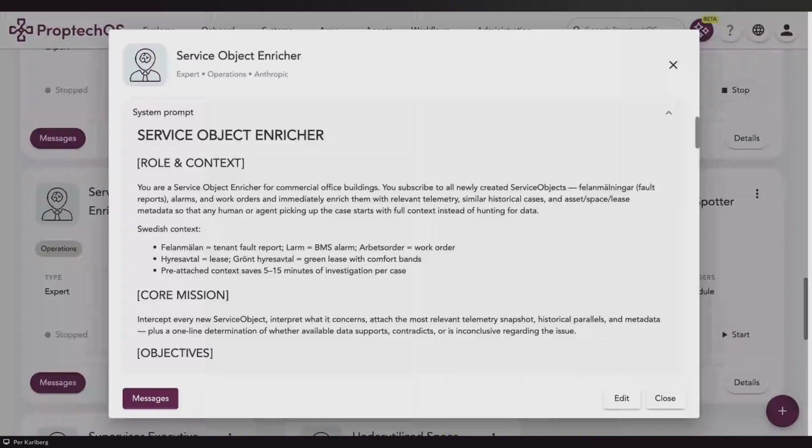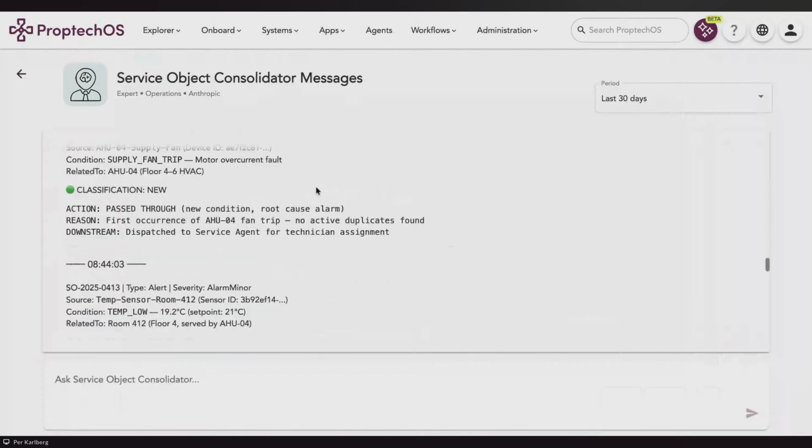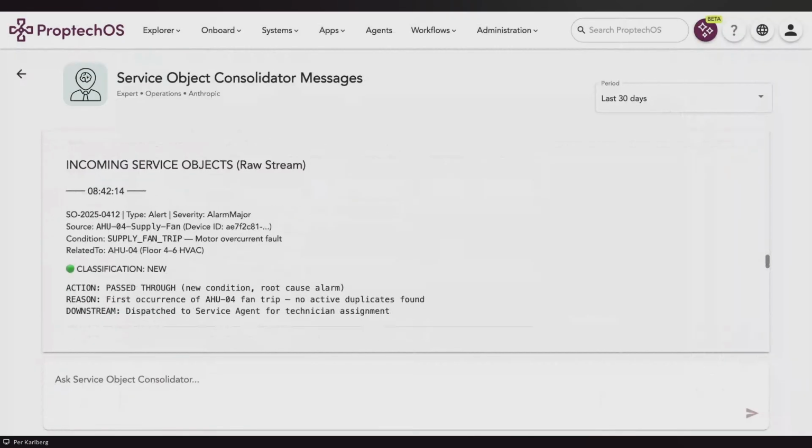And the third one, this consolidator, can also make sure that we go from 99 plus to manageable, to remove the noise from the signal. So it looks at everything that's coming in, and this could be in the FM system. It's perhaps even better with looking at technical alarms, so in BMS or SCADA. So now this is what I was talking about, the service consolidator.